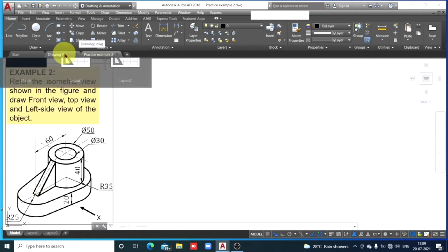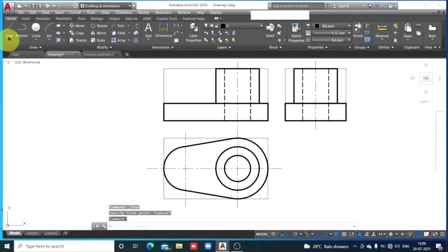Okay, so let's come to our drawing again. From the extreme left of our object, move the cursor to the right side, type 25, enter. And check here, we got lines not at the required position. So escape.